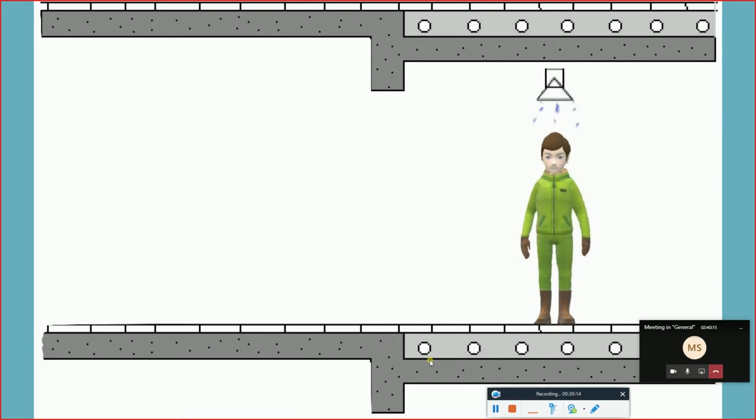Okay, so what we normally do, we sink the slab, put the pipes, and then backfill. So this area is backfilled. It's backfilled with lightweight concrete or with soil, and then finally we are going to have the same level here. So once again, we are sinking the slab, lowering the slab, putting the pipes which are required, backfilling with the light material, whether it's sand or lightweight concrete, and then we're having the final finish.